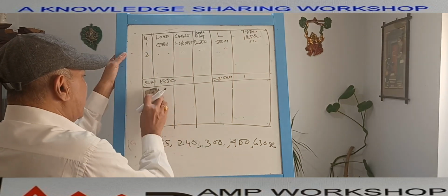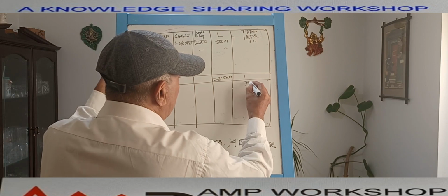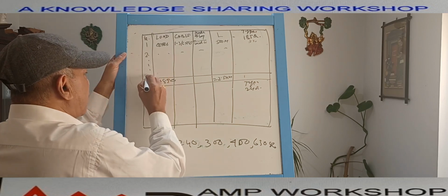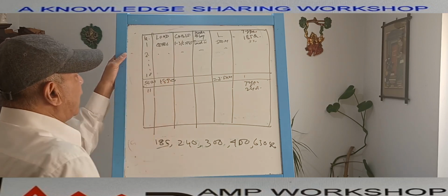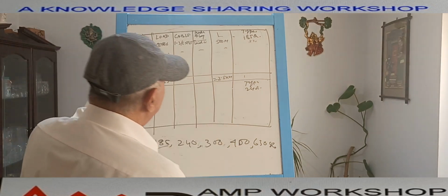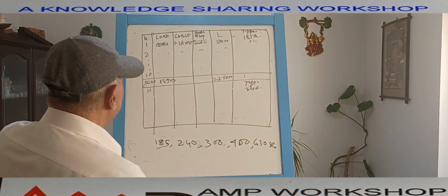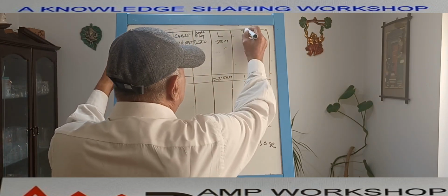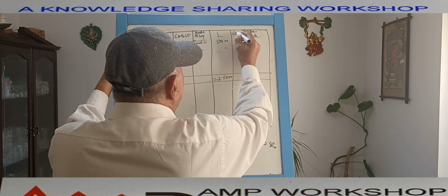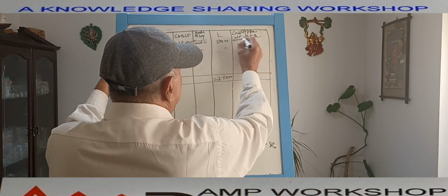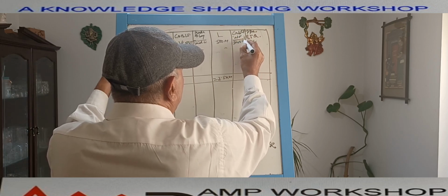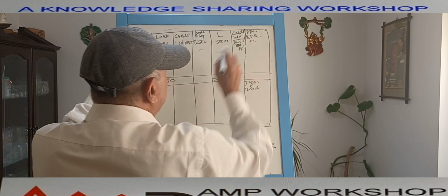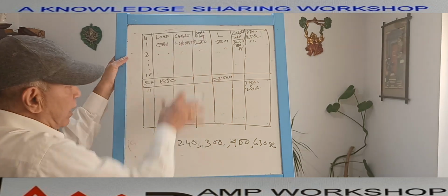Now we go to the next. We are going to type 2. Type 2 is a 240 square millimeter cable. Similarly, suppose this goes up to 10, then cable 11 will go like this. Here also we can add another column. If we want, we can put a cable number over here. Along with the type of the cable, we can make 2 columns, with the cable number, which we have already decided. We can put the cable number, switch gear 1, colon, then transformer A, colon, then the P1. We can put this number.